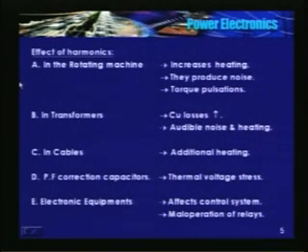What are the effects of harmonics on other equipments that are connected to the power system? I told you that only the sinusoidal or fundamental component of current and voltage are responsible for power transfer. Other components give rise to additional I square R losses, only heating. These currents will flow through other 3-phase motors. They produce their own rotating magnetic field.